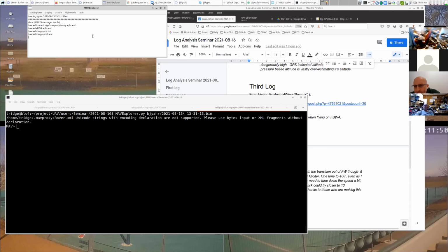But this is a slightly unusual aircraft in that it's a tail sitter quad plane. So it takes off vertical like a tail sitter, but it doesn't have any control surfaces. So it's only got the 4 motors for stability. So you run the motors all the time. You can't glide with motor off with this. If you try that, it will plummet into the ground very quickly. Has very, very poor glide characteristics, but it's a fun aircraft.